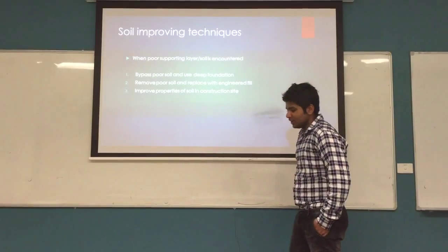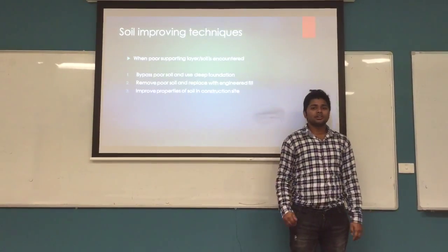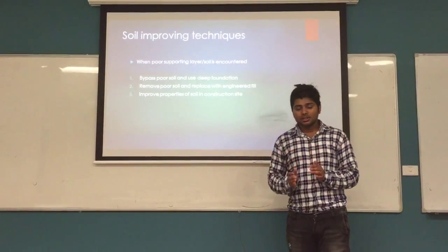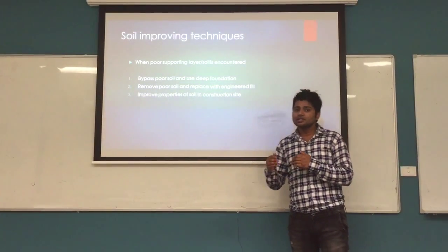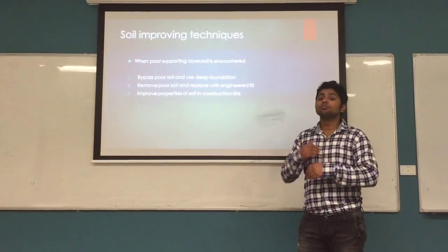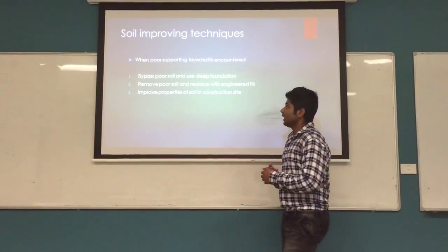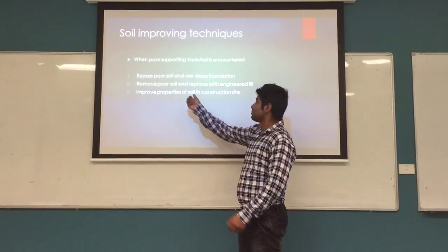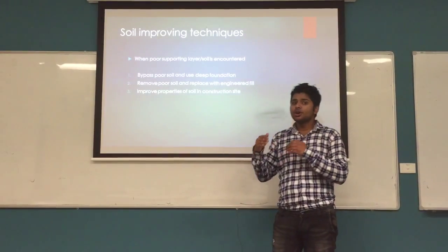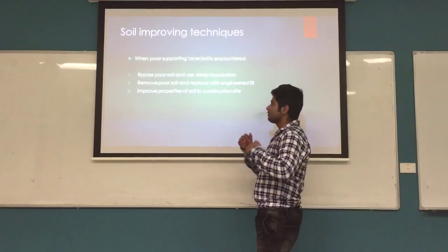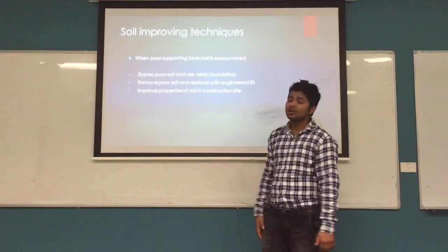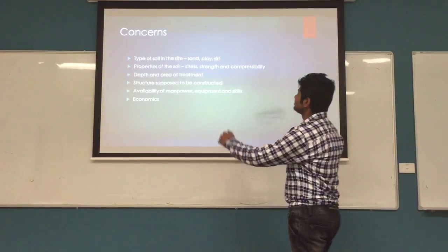Soil improvement techniques. It is also one of the significant topics that I have included in my research. Generally, different types of soils are identified on the site, and they should be improved if they have weak strength. We can use three different modes: bypass the soil and use deep foundations, remove the soil and use engineered fill, and finally, improve the properties of the soil by various methods.